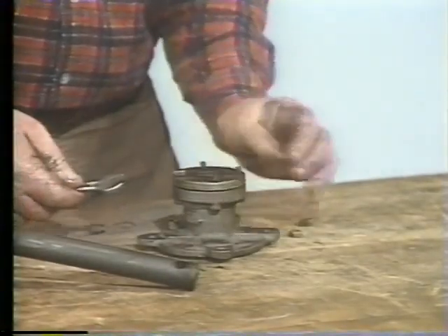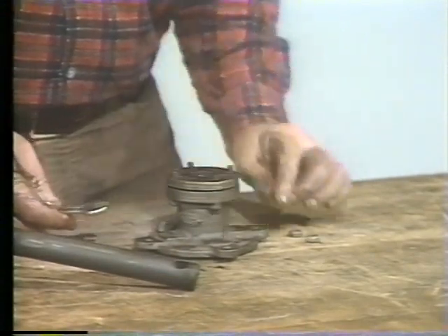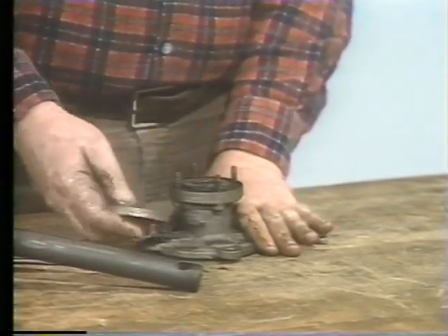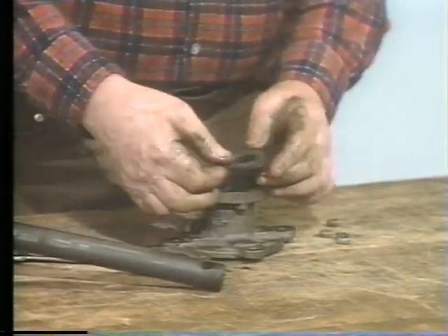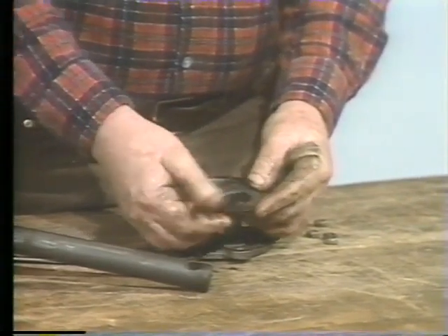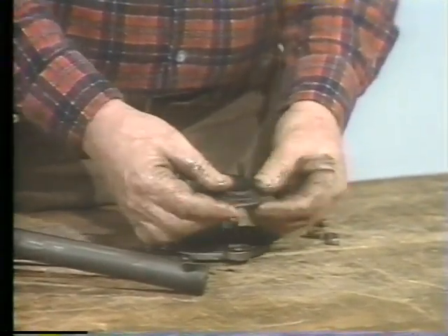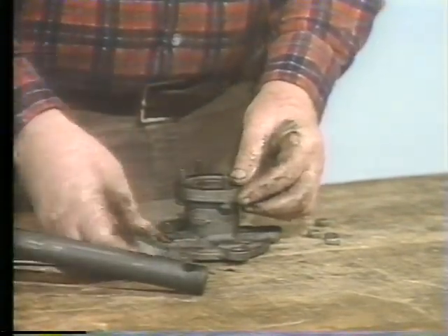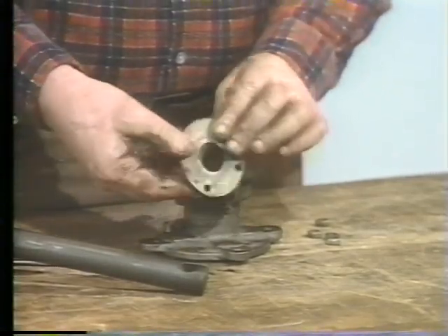As the technician removes and disassembles the end cap, we can see that it has a flange packing cover, which is held in place by 4 small nuts and bolts. A cover holds the packing, which prevents air from leaking past the piston rod. This area is a common source of leaks in piston actuators. Leaks at this point can often be stopped by tightening the packing cover. If this does not stop the leak, the packing will have to be replaced.